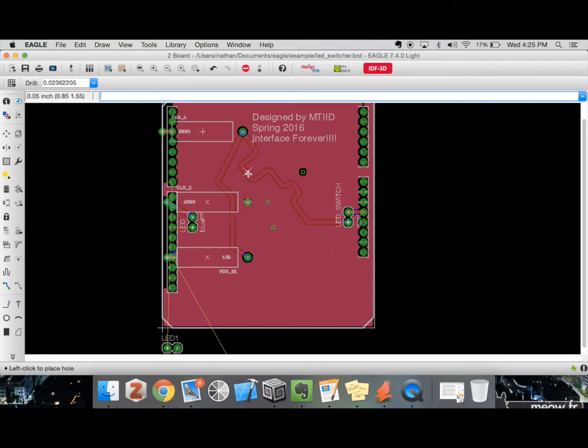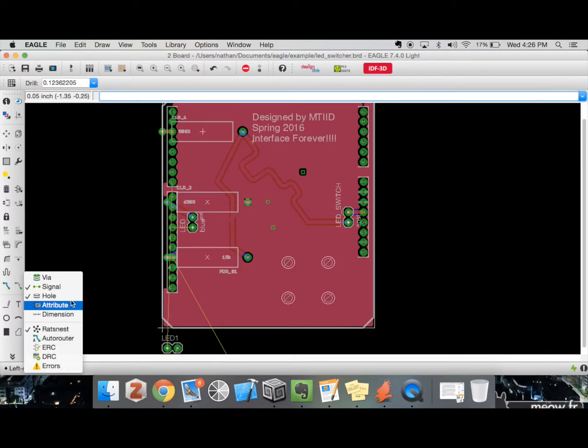Let's say we make these bigger, so we can set up 4 of these drill holes, and we can carefully measure the distance that they are on the accelerometer. We can put these drill holes into our shield. When we get the shield, they will be drilled out. And then we can put some spacers on top of the drill holes, and then we can attach the accelerometer directly onto the shield. So you can do nifty things like that. Drill holes are pretty handy.